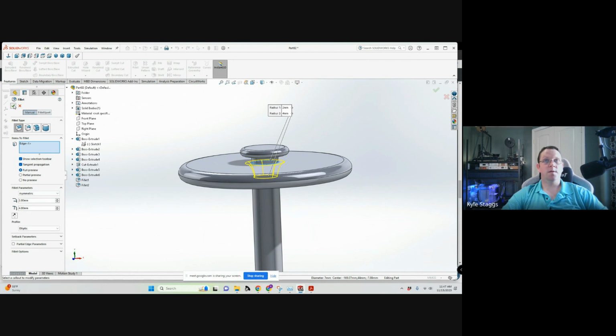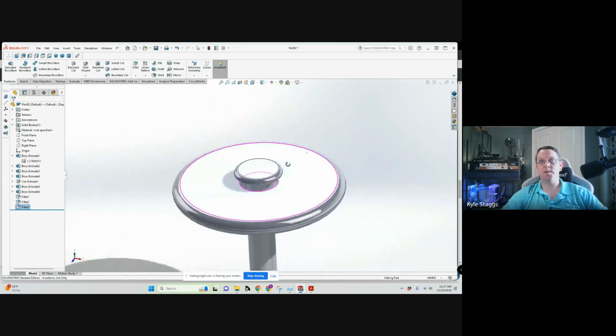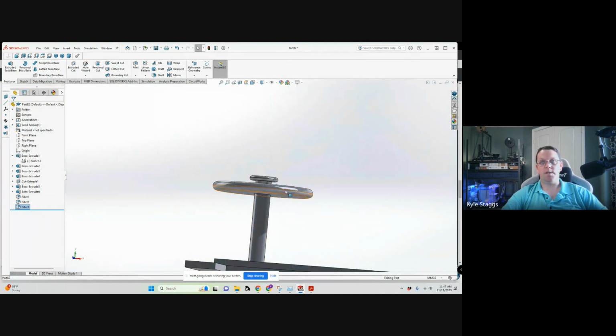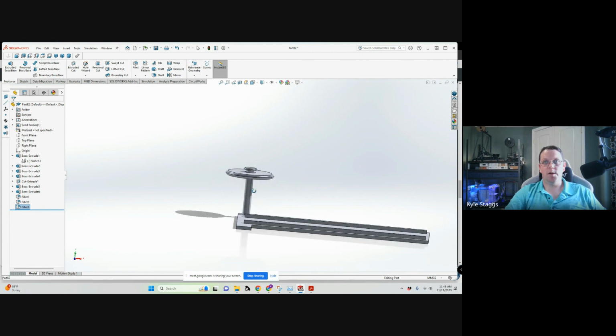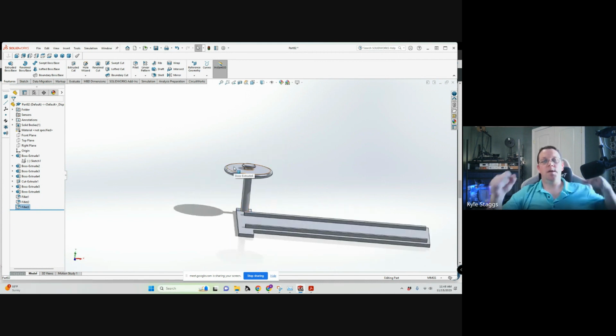2 and 4 or something like that. That'll give you some additional clearance. So lots of ways that you can do it so that when you get the print, you carefully hold the base and you twist this top piece and it'll shear off, and then you have a twist print-in-place roller. Downside is that it can add a lot to print time, because they have to do support material and things, so it's not as fast and efficient.